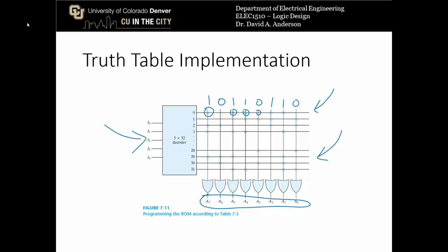So this is the type of ROM that you would see on a little integrated circuit chip that would be used in a microsystem. However, other types of ROMs, like CD-ROMs, are obviously pretty different. Those have to do with optically coding the bits on the surface of plastic by using laser reflections. So this basic principle would apply to all ROMs, but the actual logic circuitry that we've explained here really is only relevant to integrated circuit ROMs.